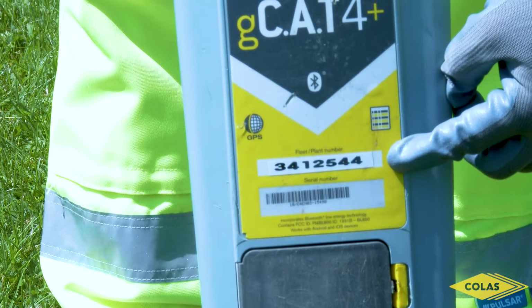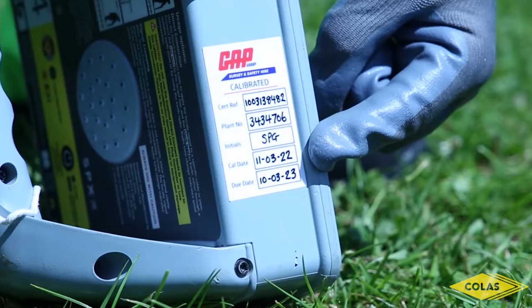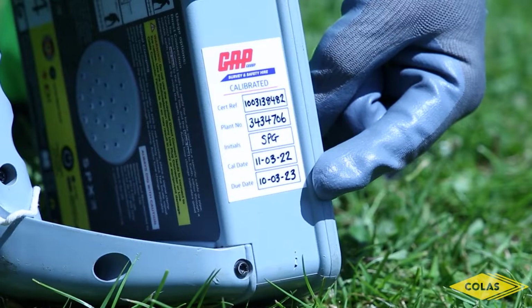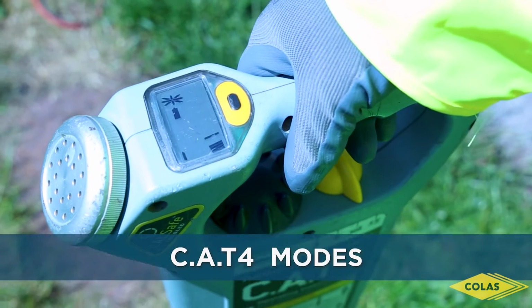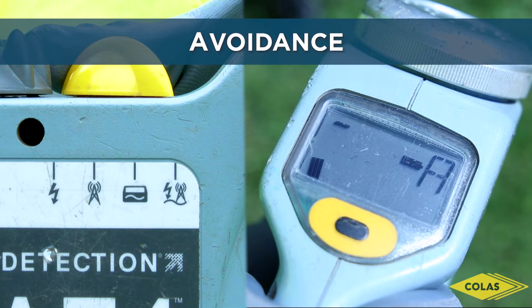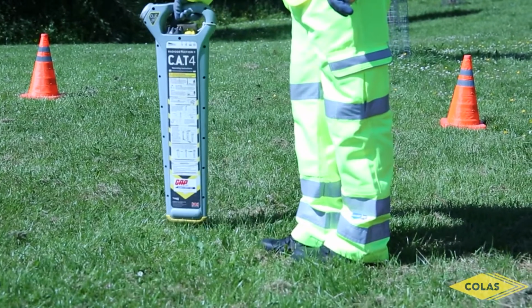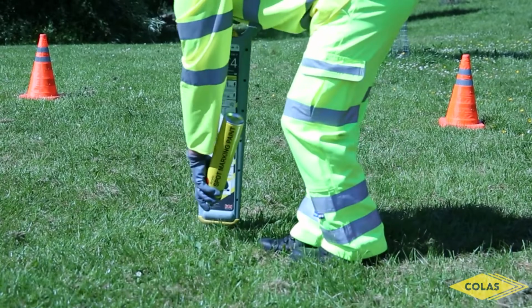Also, on the CAT device, you will find a serial number and a calibration date. Ensure that the calibration is in date before use. The CAT device has 4 different modes. Avoidance. This uses all the modes at once. It's advisable to use this mode first when carrying out a locate.